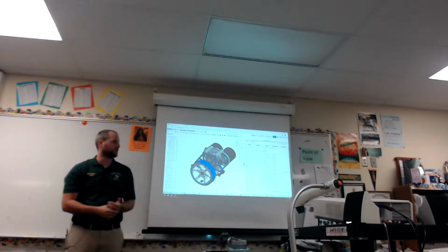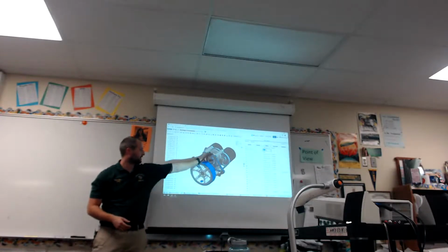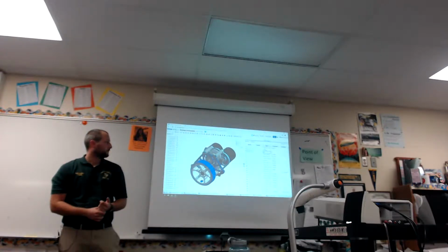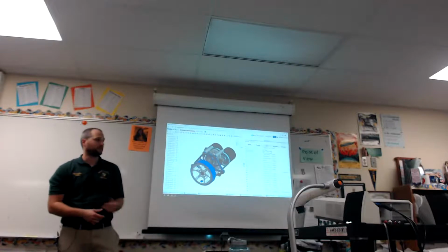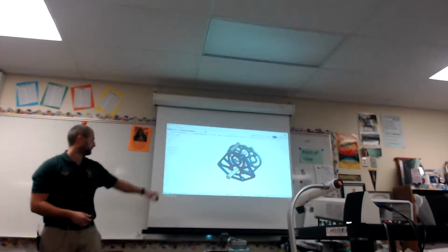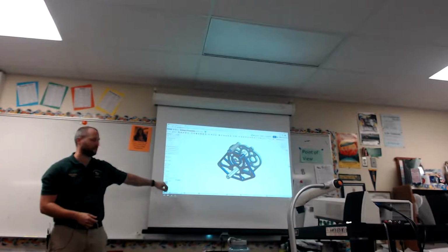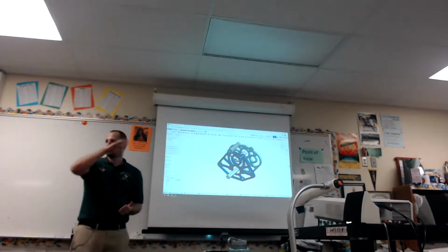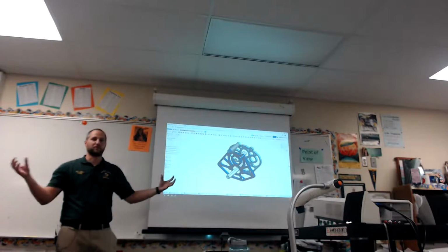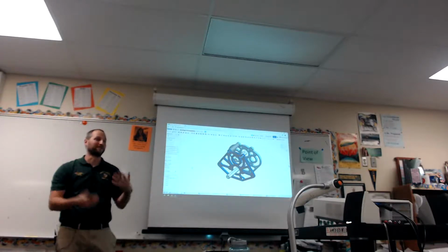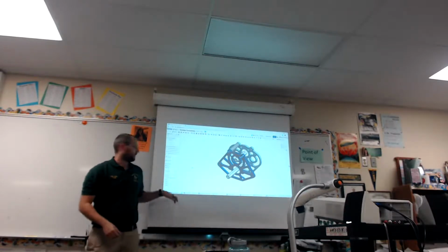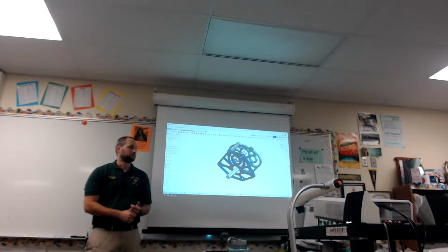And Tony's going to change the name of part 2. If you hover over it, it highlights it. That's all those spacers. He's going to call them the spacers. And he's going to go back to our Part Studio demo. It's kind of hard to see. Sorry, this resolution's not great. It renamed it from part 2 to spacer in the Part Studio as well. So if you end up going all the way through, or you have multiple Part Studios where you're pulling parts together and you have 4 Part 1s and 5 Part 2s, you can grab them in your bill of materials and rename them there, and it'll propagate backwards as well. It's kind of nice.